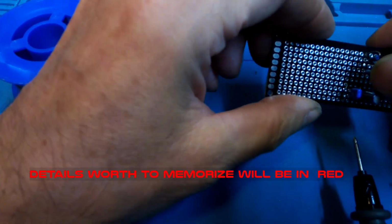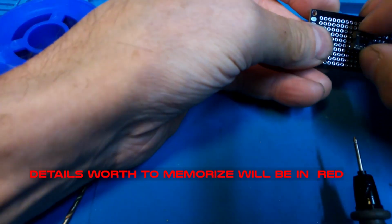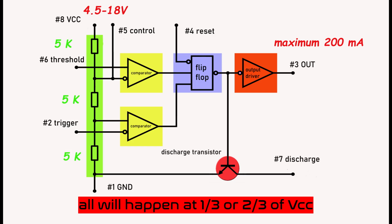Okay, let's start from the beginning. What's inside this small plastic package? This is the internal block diagram of this chip. From the left, what we see is a voltage divider. It's 3 resistors of the same value between ground and VCC, so everything will happen at roughly 1/3 and 2/3 of the power voltage of VCC. Then two comparators, a flip-flop, an output driver and a discharge transistor.